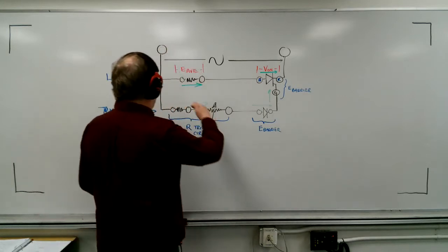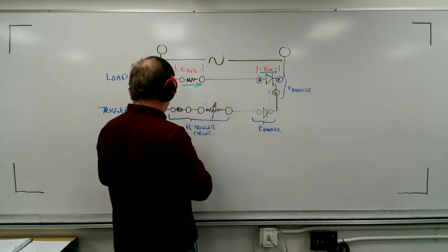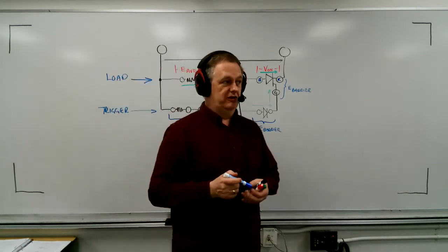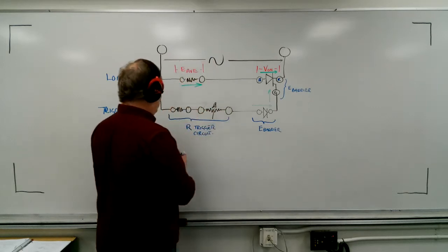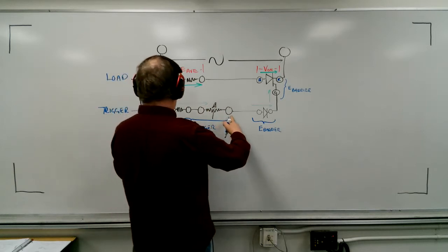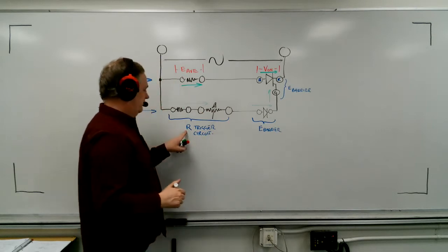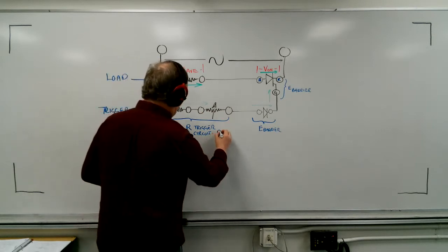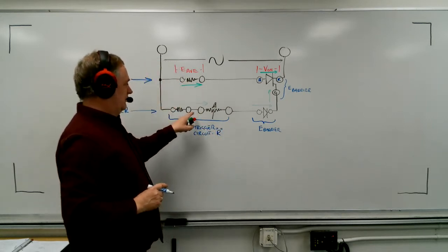when we are dealing with this circuit down here, the trigger circuit, because the currents are very small in this circuit, every little bit of voltage is important. And so that's why we look at this and we say, the amount of voltage drop across the resistance, we're going to call that the resistance of the trigger circuit, the resistance part. And that's how we're going to actually determine the current.